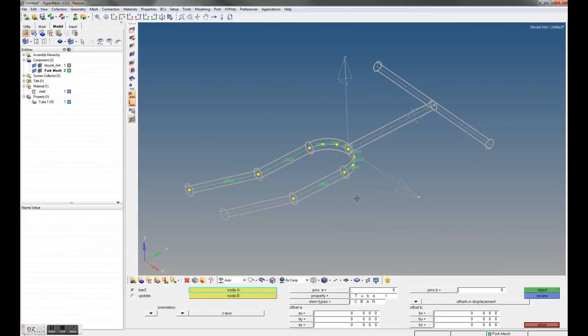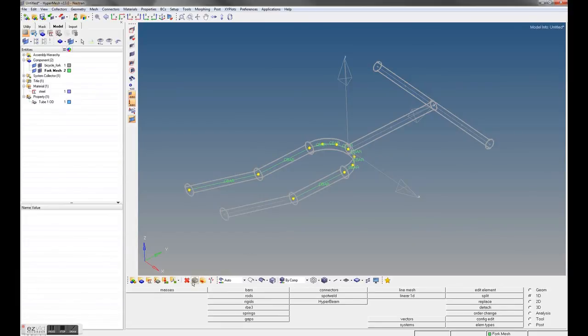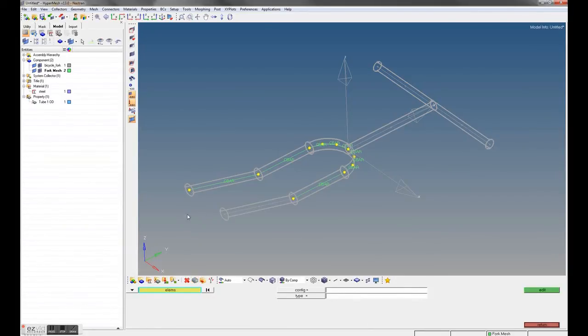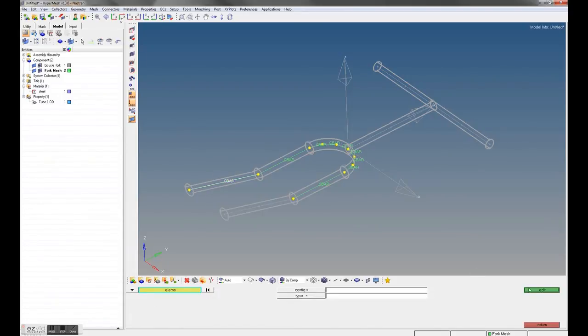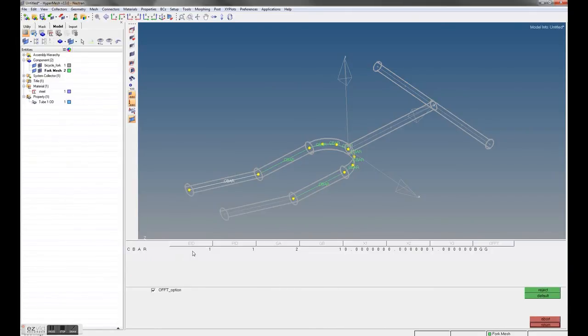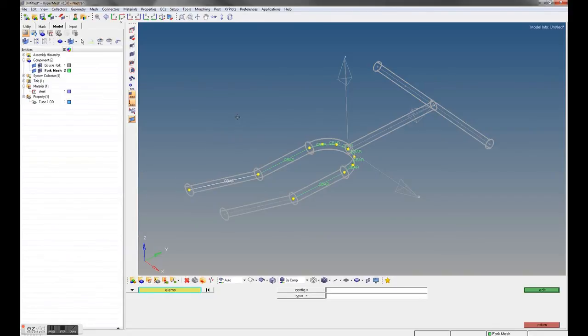All right. So now you have a mesh. You can actually check the elements if you want. This little thing that looks like a couple of manila folders stacked up, that's the card edit. If you change this to element, you can pick an element and say edit, and then it'll show you basically the input deck, okay? So that's pretty much how you can go about making the geometries you need to.